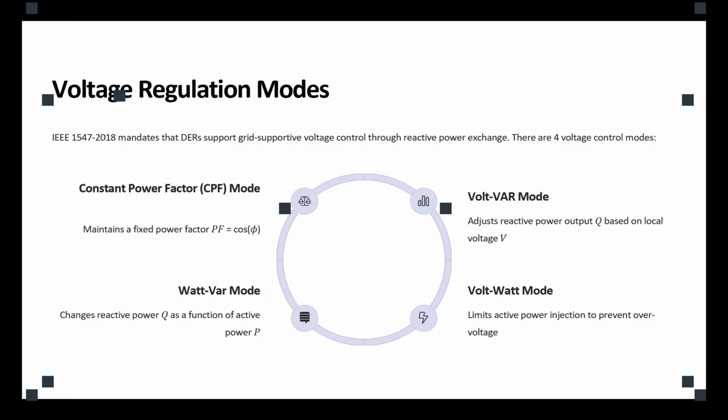We said in the previous slide that there are three options we want to control in fault ride through: voltage level, reactive power, and power factor. That means we have to optimize the situation to keep the power factor in constant mode. This is one of the requirements that we have to add to our control system.